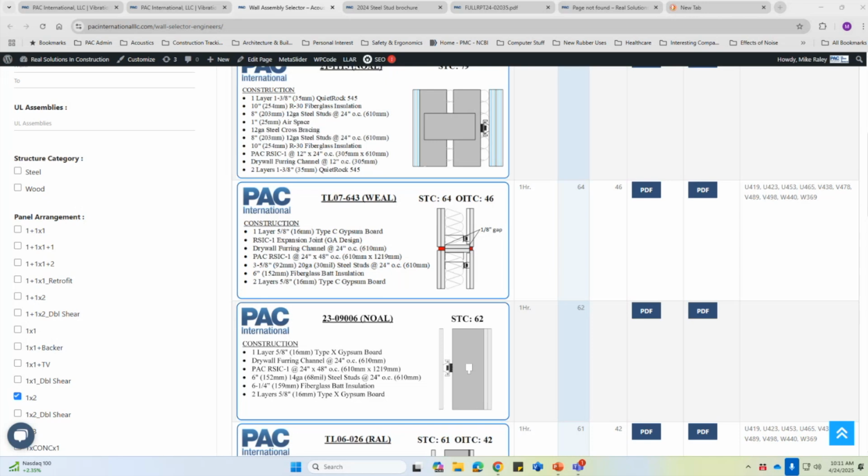And if you try to use mineral wool, which I know a lot of people commonly think is better acoustically than fiberglass, I take issue with that. But it is a much higher density and it's much stiffer, and so you can't compress it nearly as much before you start getting some acoustic transmission from side to side. So yeah, that's another good point.